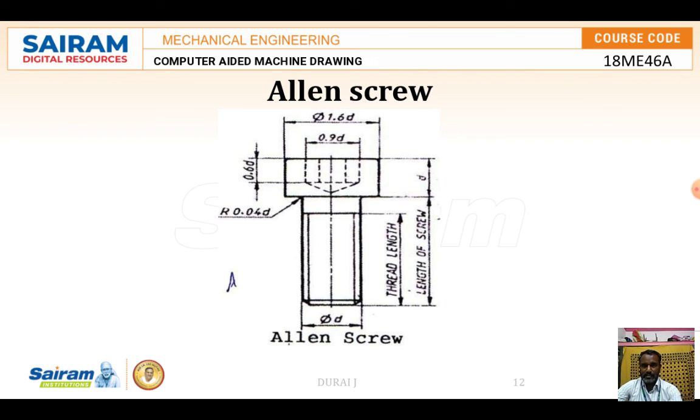So in this PPT, all the values related to D, whether for the countersunk, Allen screw or grub head, all those values and formulas we have to remember. With the help of D, we can calculate the values. The remaining things we have to design and draw in the sketch as well as in the drawing mode of the Solid Edge software.